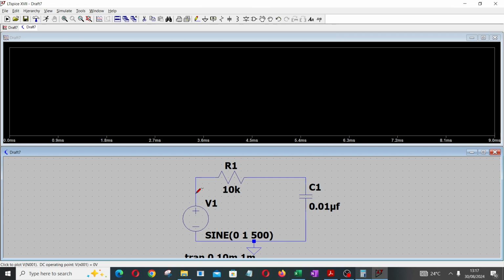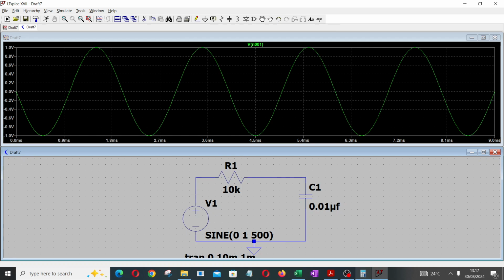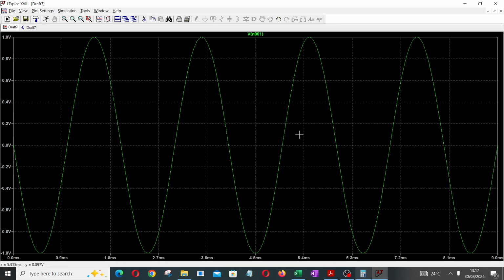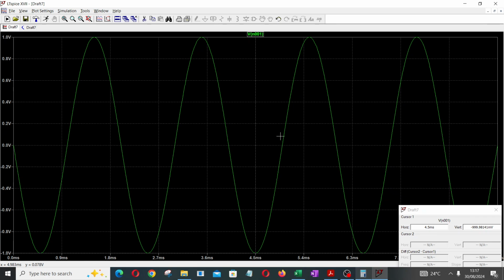Let's first of all measure the voltage supplied by this system. Click your cursor around here. The waveform will appear. So when you want to measure the frequency, what will you do? To measure the frequency, let's try to maximize this waveform so that we can have a better look. When you look at the waveform, it runs from 0, minus, back to 0, to 1, and so on and so forth. To measure the frequency, take your cursor, click on this voltage representative here, then try to track the point where the signal is.